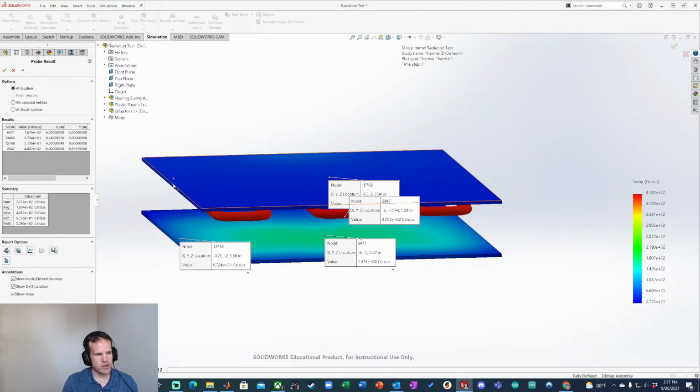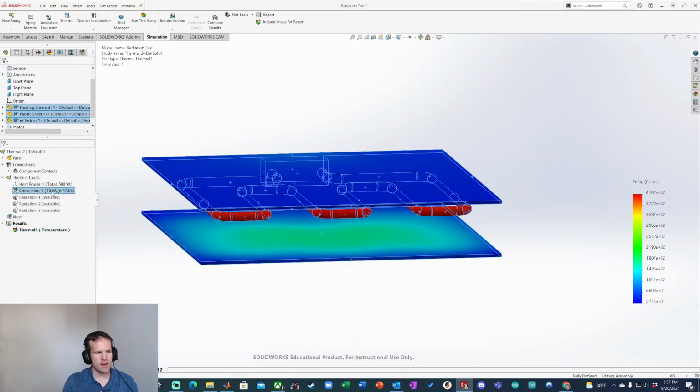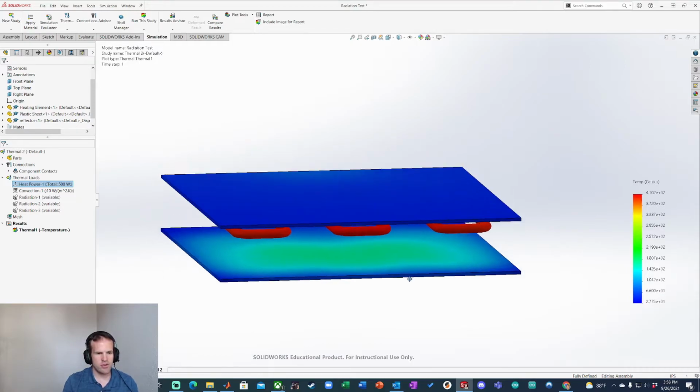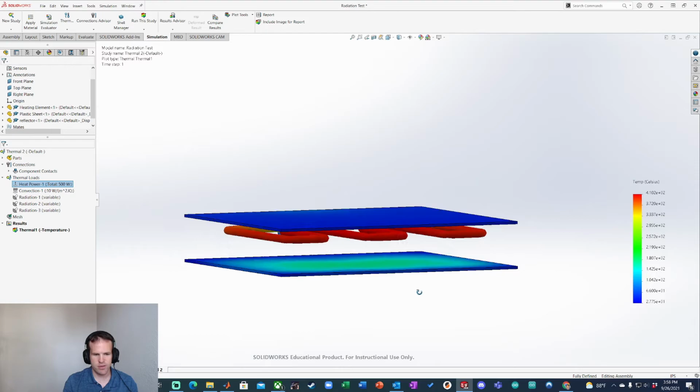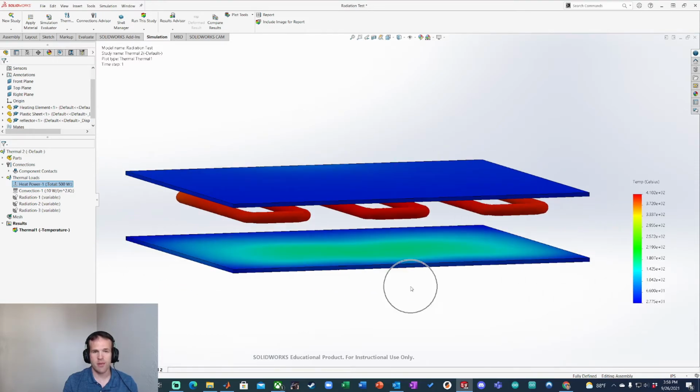And we could then tweak the results to see how these different parameters are going to affect it. Like maybe I have more or less convection. Definitely if I have a different kind of heater, more or less powerful. And even these radiation variables, especially the emissivity parameter, if we have better data of the material properties, these can all help us refine this simulation. So hopefully that gives you an idea of how to use a SolidWorks thermal radiation study for just a simple steady state example. And you can use this for design purposes.